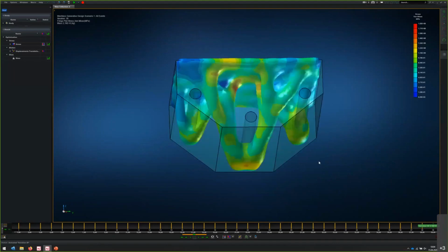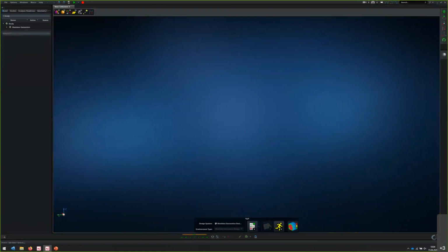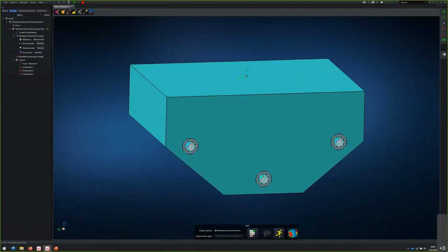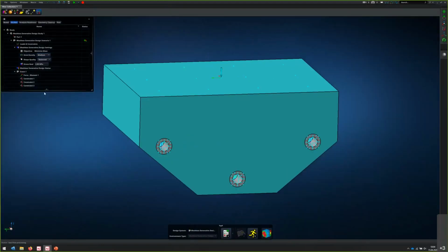Because if you want to go for the real maximum stress the material is capable of carrying, this is mainly much too little material, and as well you will get some durability problems if you go for that critical value. So for aluminium, you have 430, 450 megapascal, and we are mainly optimizing for something like 50 or 60 megapascals, getting much more lightweight designs than before, but having a big safety factor inside and very good lightweight designs.